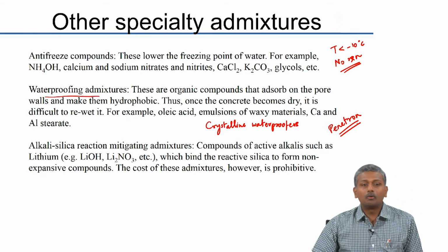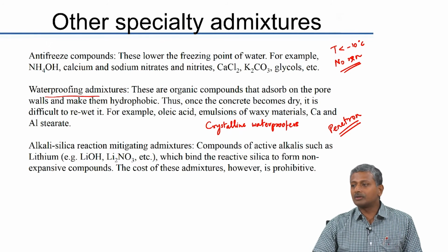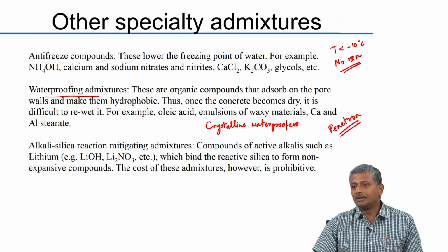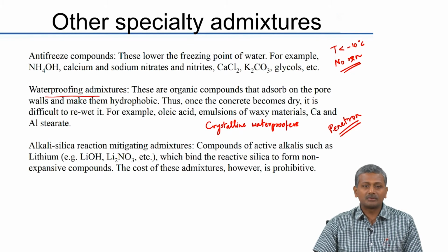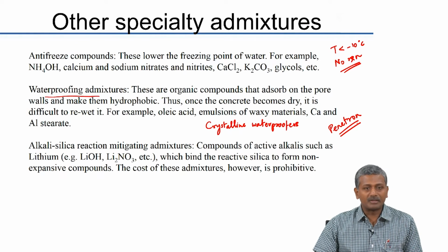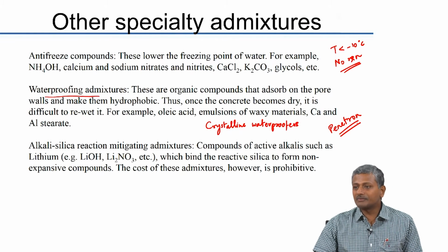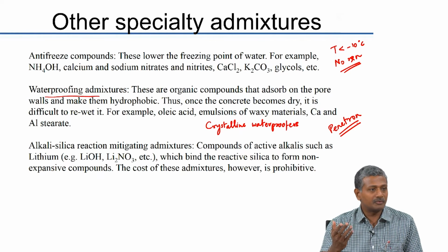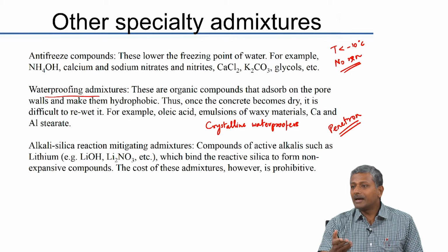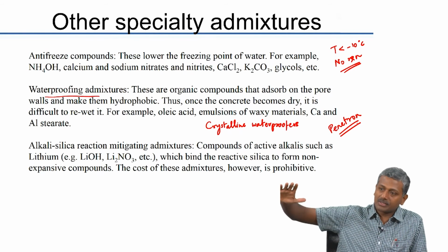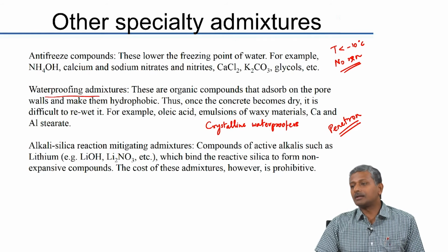Okay. Now, because the contractors thought they were using a waterproofing chemical in the concrete, they sort of avoided the other systems which are important to keep water penetration in place, like the use of water bars, for instance. And because of that, what happened is, when there was this flood, we had very heavy rains in 2015, and even before that actually there was a period of very heavy rain, and a lot of water actually started gushing into the utility tunnel.